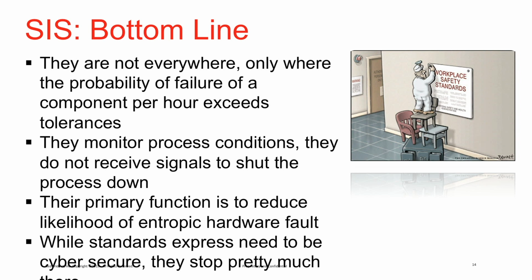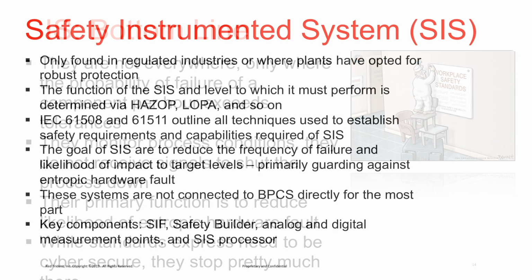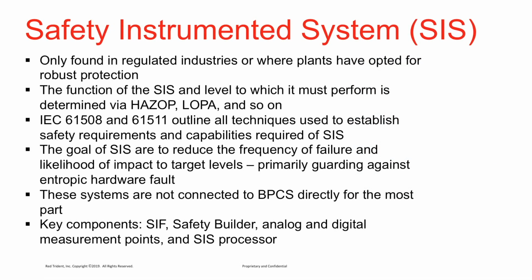And soft interlocks, if you really are using those and you have a truly dangerous process, you need to start thinking about upgrading that to another SIS. The risk equation, risk is what? Risk equals likelihood times consequence, right? We're dealing with the same consequences from a worst case scenario perspective. It's the likelihood component that's different, right? So in safety, they're just going to measure, here's how often it's going to happen. In security, we're saying, here's how likely it is that I'm going to make it happen.